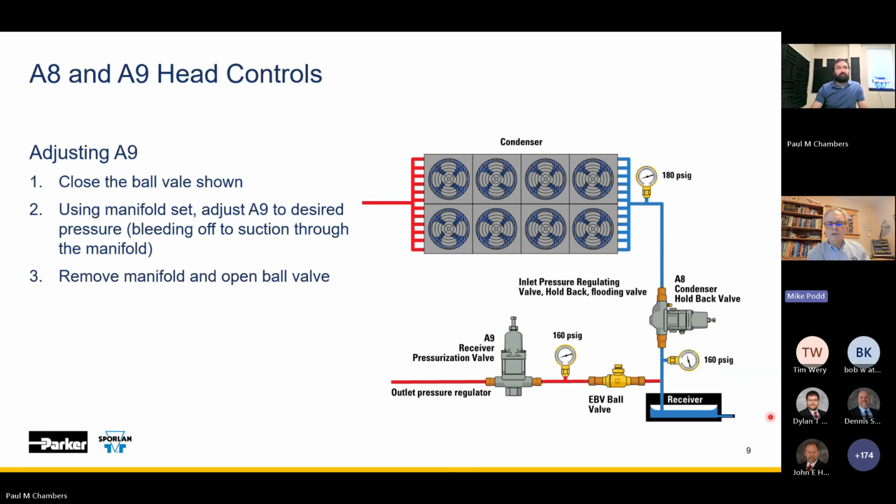For a little more clarity, instead of having that high pressure valve tee into that condensate line, it could go right into the receiver. You're just really pressurizing the receiver. That's just a function of that. It's helpful because our other devices tie into that.